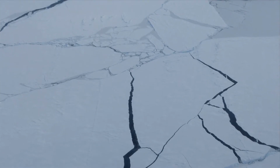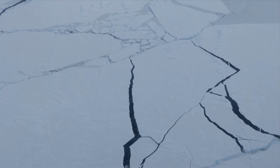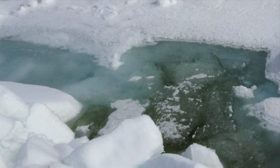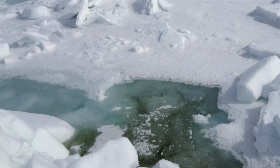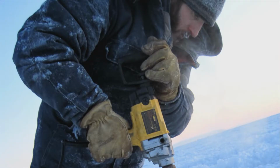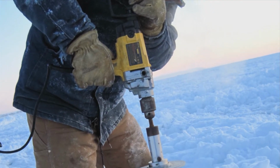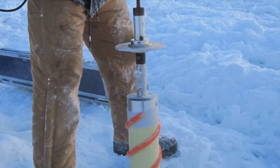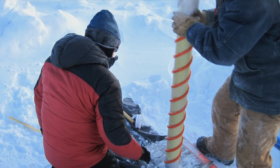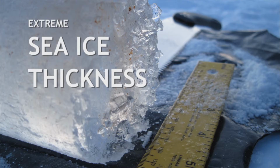So when we're talking about extreme thicknesses, there's extremely thick level ice. This is ice that hasn't been deformed and piled up into sort of big mountains or ridges of ice. And extremely thick ice of that kind would be nowadays 4 to 5 meters thick. And we don't really see that so much anymore. One consolidated solid sheet of ice. And that would be a significant obstacle to an icebreaker or a hazard for a fixed structure, like a drill platform or some other structure.